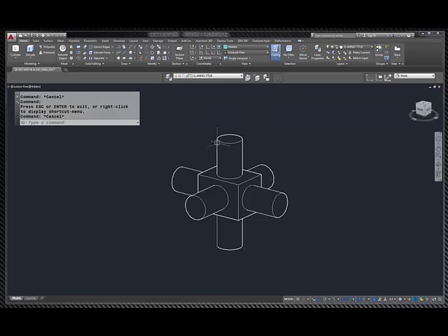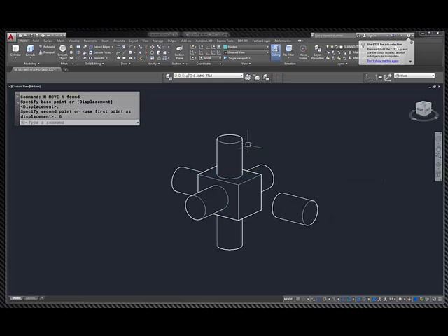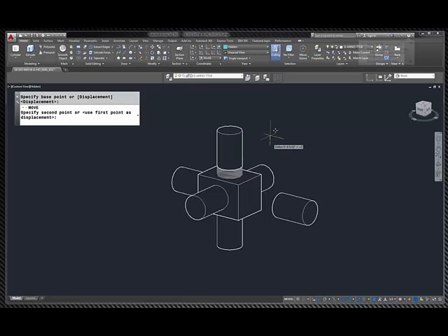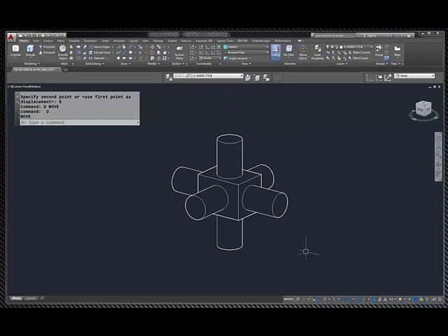Okay, I want to manipulate these. So we've now have this. Now, these are all individual pieces, okay? So I can just go M for move, pick a point, and pull this away, okay? And I could pull it 6, and it's 6 inches away. Okay, I could take this and 6 inches away. Okay, so we have that ability. I'm going to undo both of these. There we go. So this is all about how we create the objects up here using the solid blocks, okay?